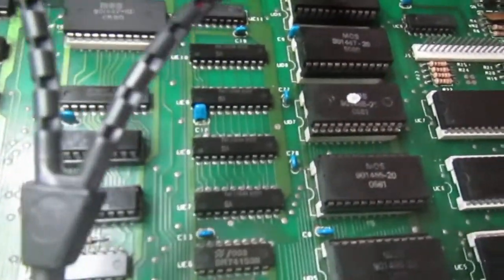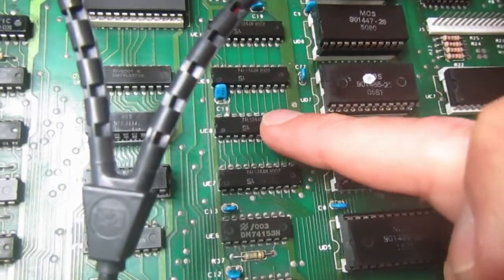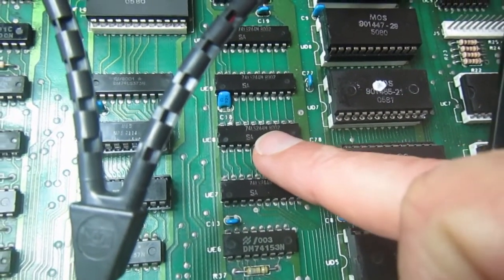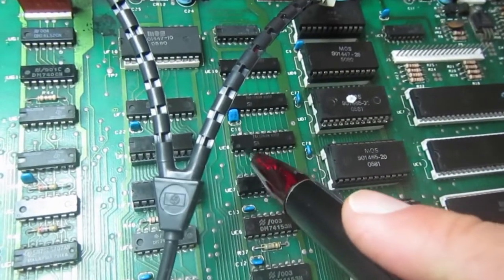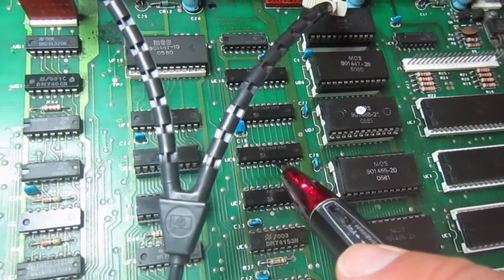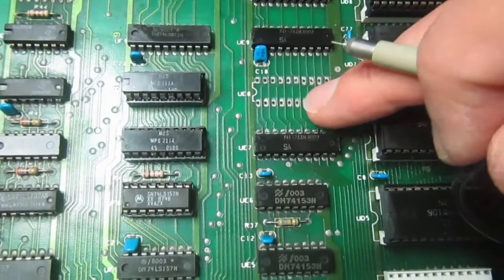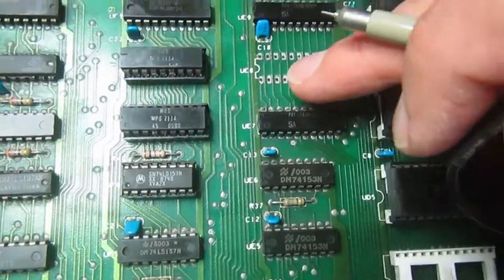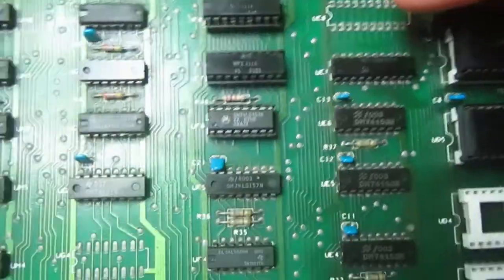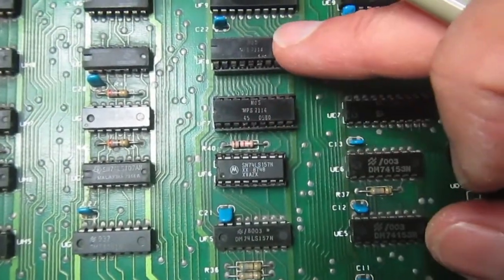So there may be more than one issue. Anyway, I think I have to remove and replace this 74LS244. With the lifted pin, it should not make any conflict on the bus, as it's still doing. So I removed the 74LS244 at UF8, but I didn't install a socket yet because in a previous repair attempt the two video RAMs have been socketed,